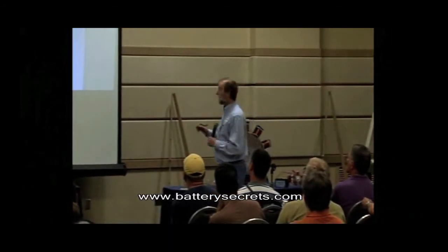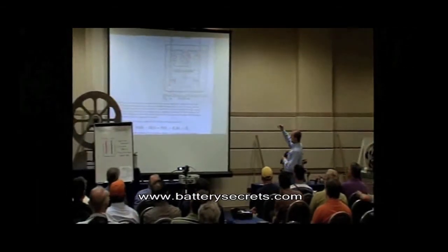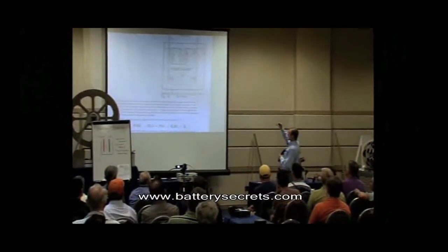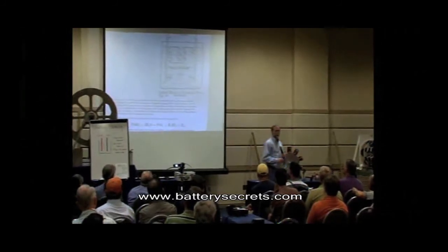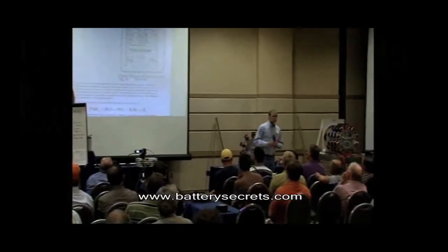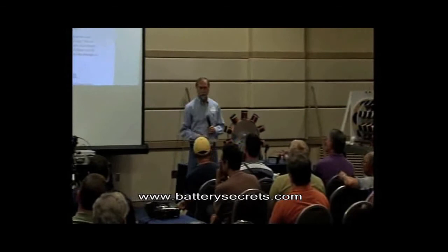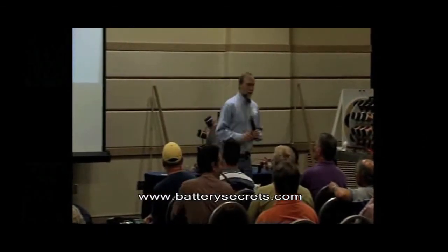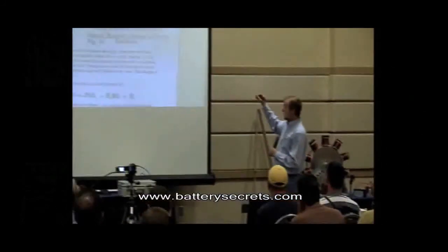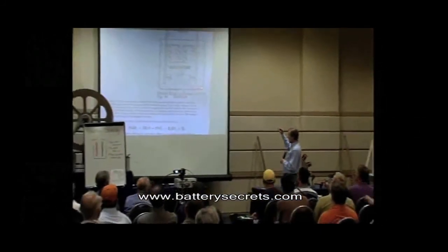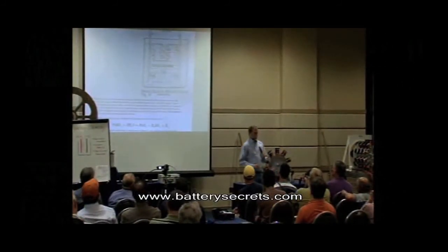It can. Now, what happens is you'll notice there is a distance between the bottom and where the plates end. Now, I'm sure you've noticed when you've bought a battery for your car, you can buy a 24-month battery or a 36-month battery or a 48-month battery. And if I told you that the difference between a 36-month battery and the 48-month battery is a 1/16 of an inch down here, you'd begin to understand the price difference.